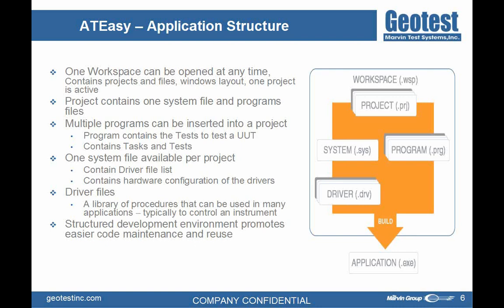And finally, the program module is where you would place code or resources specific to testing a UUT. For controlling the instrument to provide stimulus to that UUT, to set up your switching, to route the signals to the various locations, and then to take measurements and perform evaluation on those measurements to determine the pass-fail status.